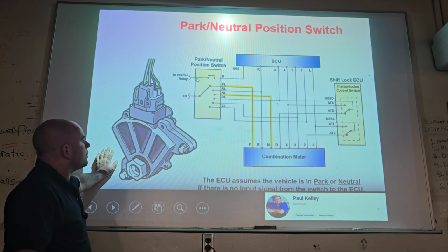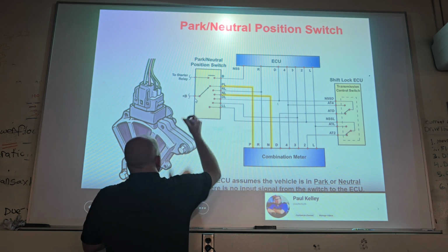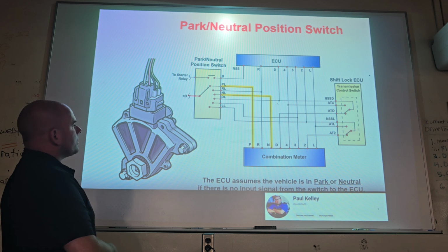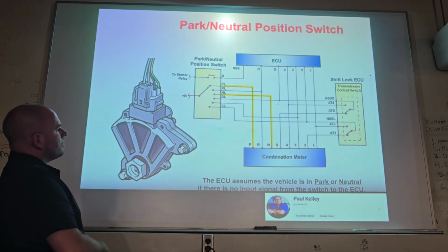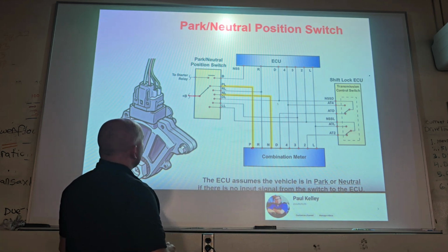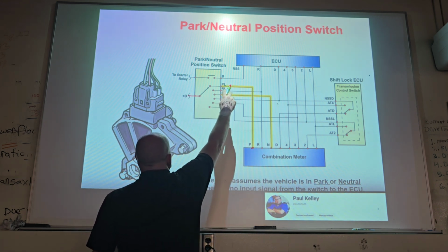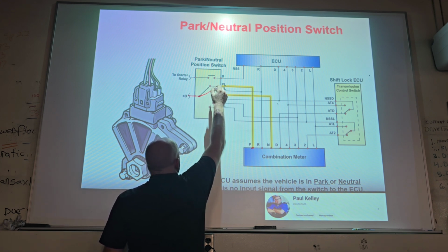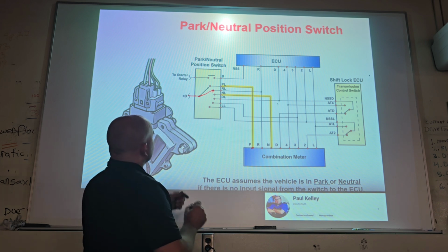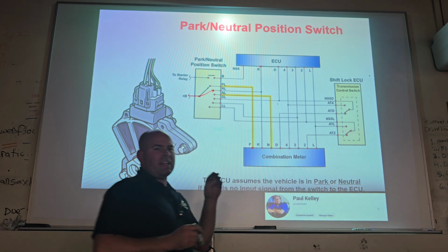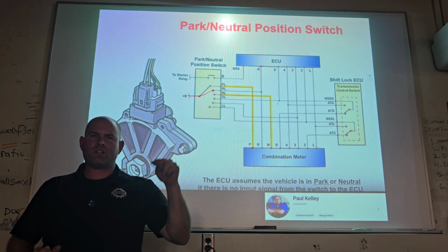So if you look at this one, let's say we send B plus, you see this? B plus is red. Right now, which terminal is going to get 12 volts? Just P, so the actual ECU doesn't get anything. What if I were to, and you're right, and B too, what if I were to go and put it in reverse? Which one would get it? Can you see it? The R at the ECU. Make sense? So that's how the TCM knows where your shifter position is.